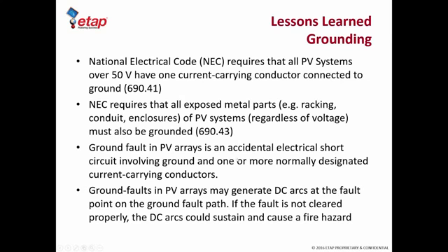So there is a DC arc flash calculation module available inside ETAP to help you make sure that the grounding is done appropriately and it is safe, especially if you're planning to do work on the system energized. It will help you understand what is the appropriate PPE to be used. Obviously, in PV systems, the best thing to do is operate on the system at night, so there's hardly any irradiance, there's hardly any generation from the panels, and most of the work can be done safely at night.